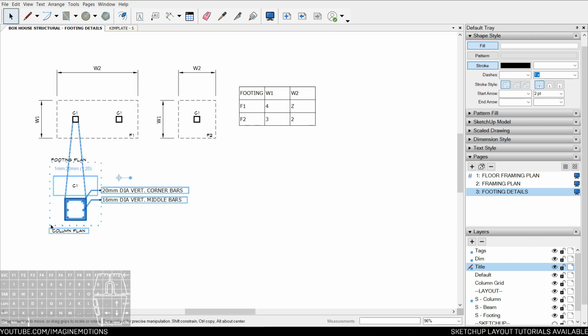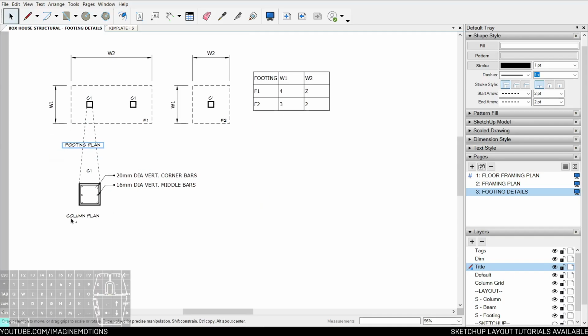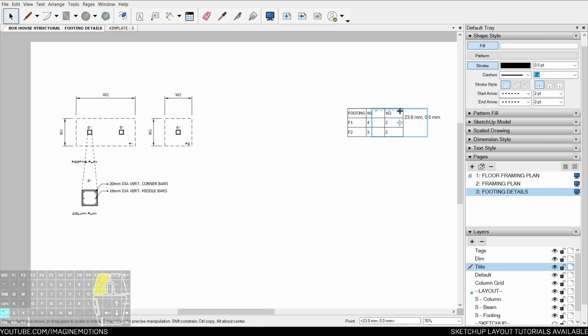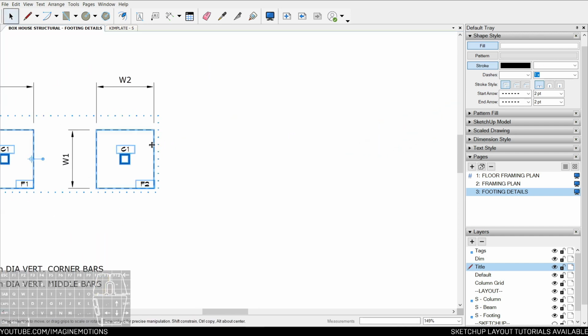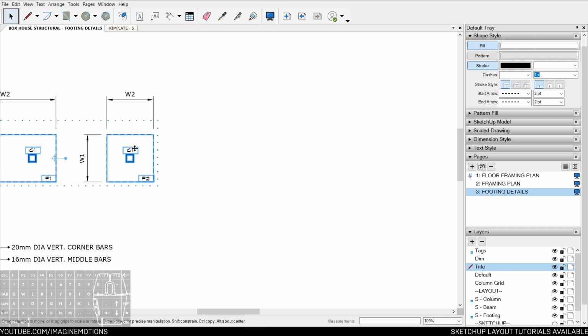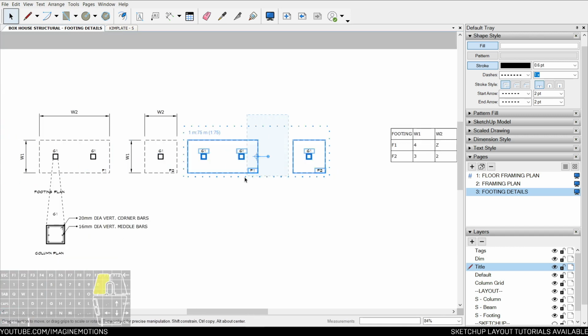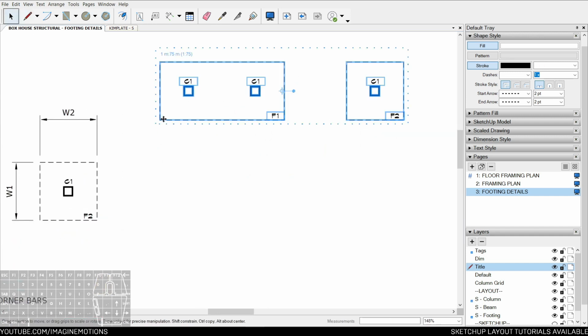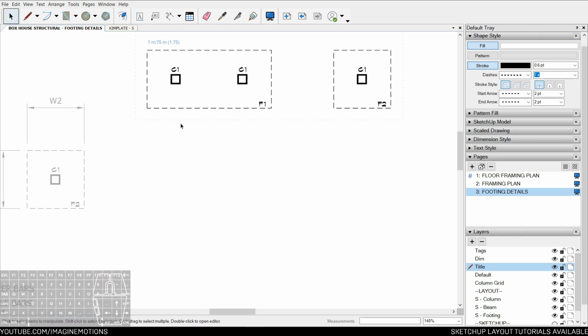Since we already have plans, we can make the sections. Remember our split and glue. You can use those techniques to make the section. Let's say this one. I want to make a section for this. So let's say I'll just copy this. I can make section for both, yeah? Okay, let's say I'll make the scale drawing inside so I don't have to rescale again. Let's say there. This will be the footing height.